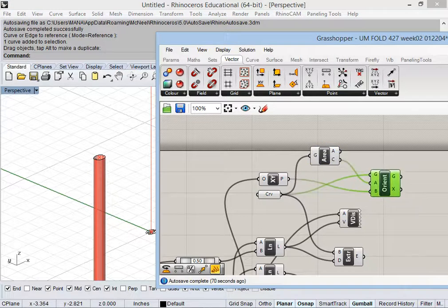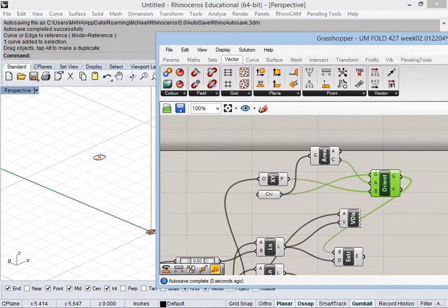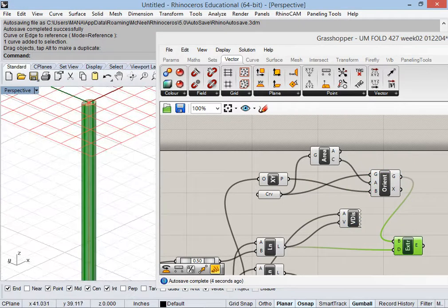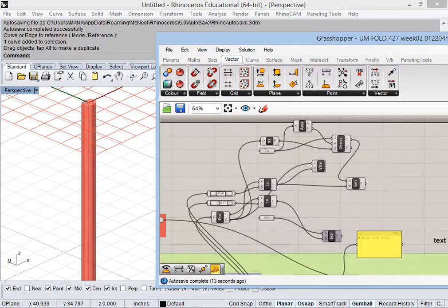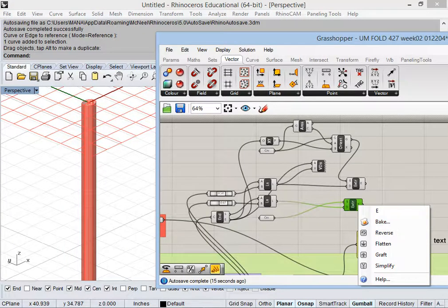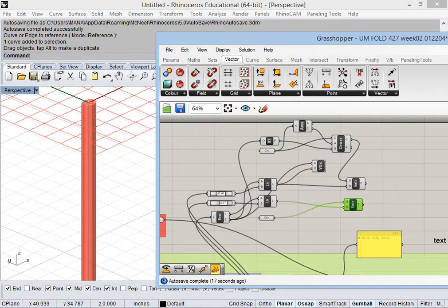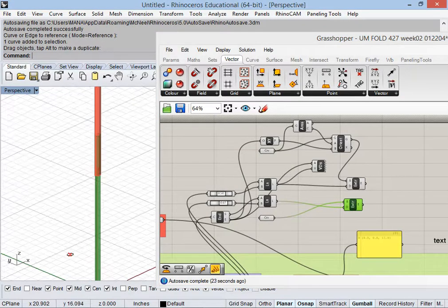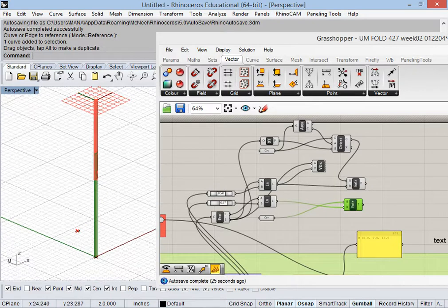Now this G is the new geometry. I don't want to extrude it from here, I want to extrude it from here. So I plug in G in for B. That goes away, and now it extrudes in the right position. Turn on this extrude. We have the two geometries embedded inside each other. It's going to get more complicated, guys, in a minute.